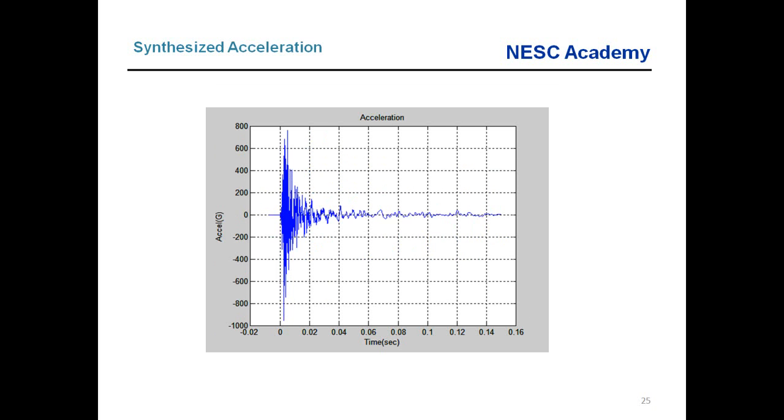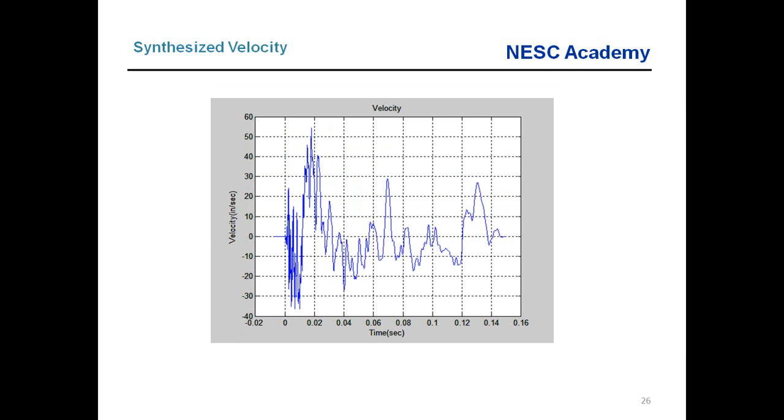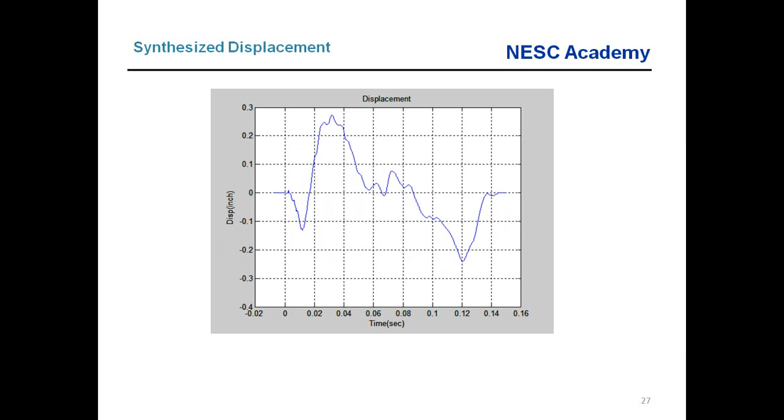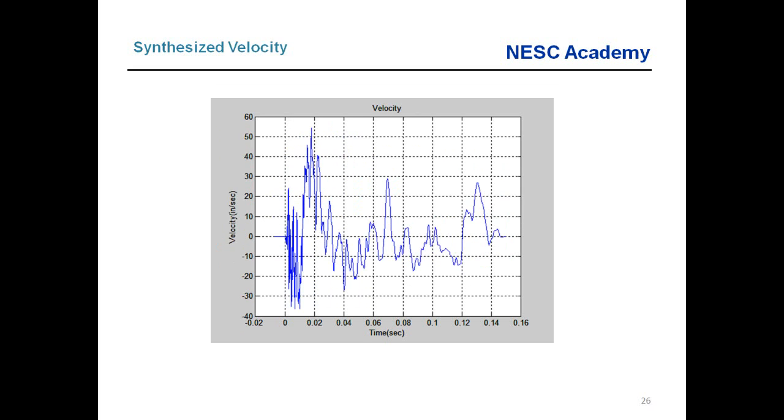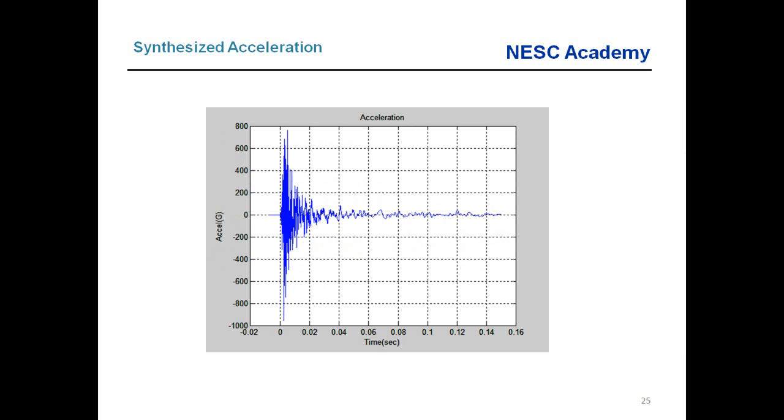So now what we have is a consistent set: acceleration, velocity, and displacement, and this indicates that the acceleration time history would be suitable to base drive a structural dynamics model as part of a finite element analysis.